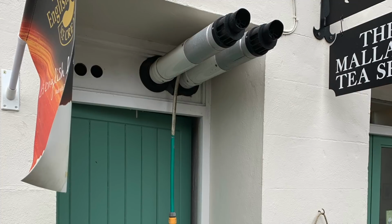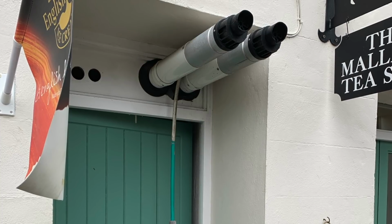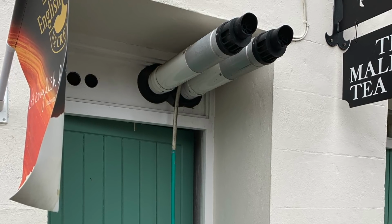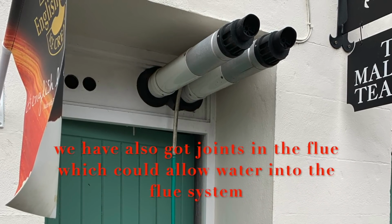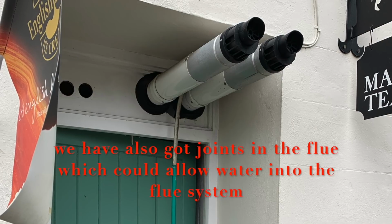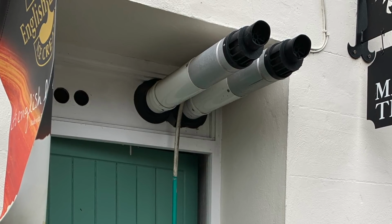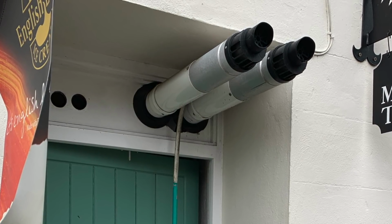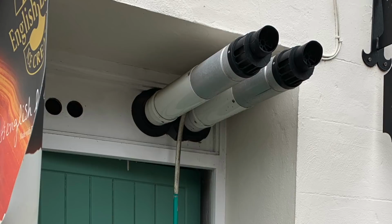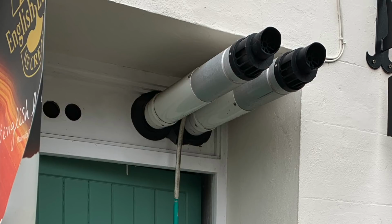So these are actually 2 commercial boilers in a commercial premises. So again, they've got the flue sticking out of the wall. Again, it's not clipped. Sticking the flue out of the wall does not make you more than 300 away from the opening within the building. Also, these flues running parallel with each other, they should be 300mm apart. So in this situation, you would be at risk in this all day long. And again, if you were getting more than 10 parts per million CO coming in through that door, then you will be IDing this installation. Again, such a poor installation.